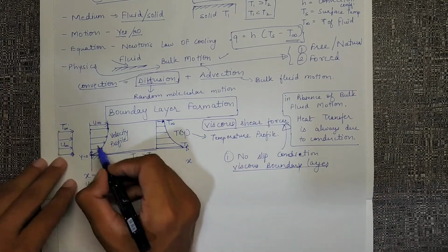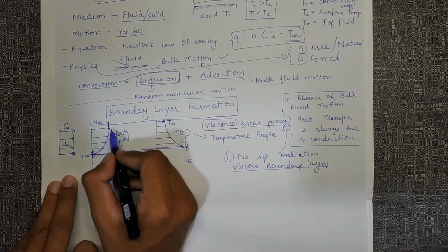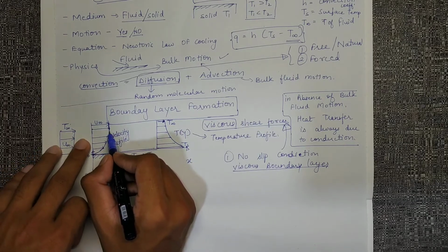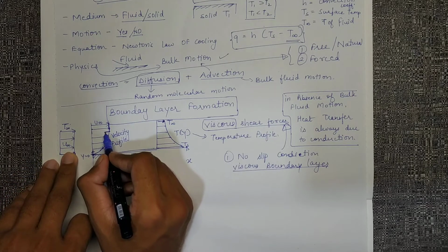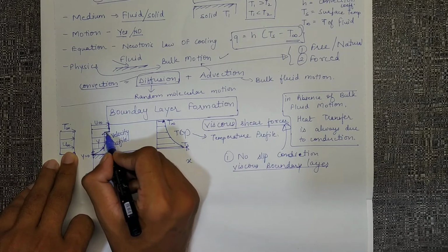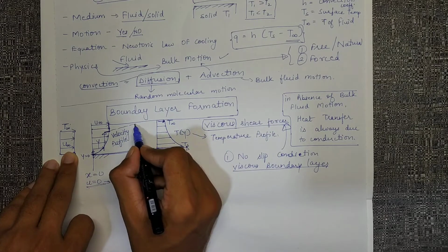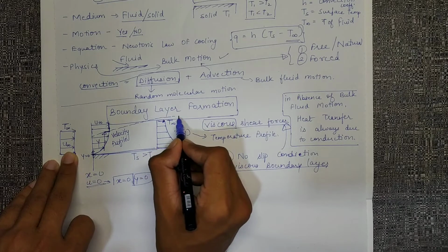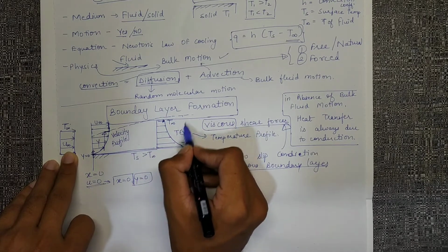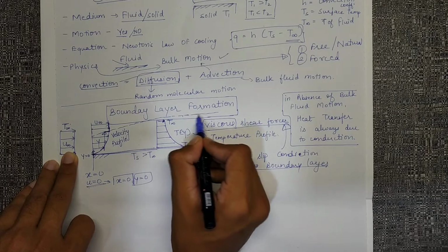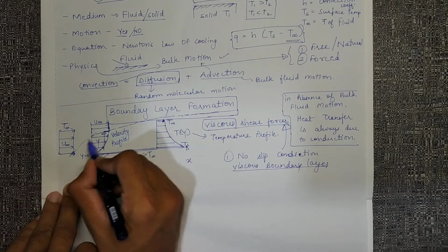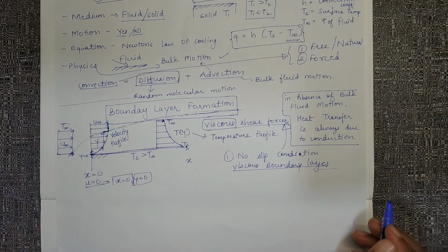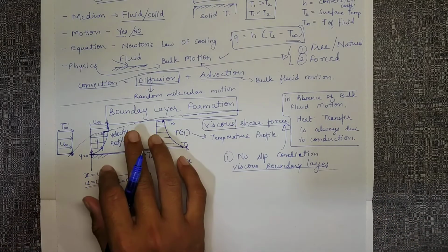And so we have the viscous boundary layer. What is this? Over here we can see that my velocity u infinity is attained at a height, let's say this is some height y, and as we go away, that y height will increase and it will then get constant after some distance on x. So this profile which we see is the boundary layer, the viscous boundary layer. And so that's all. That was the concept of boundary layer formation.